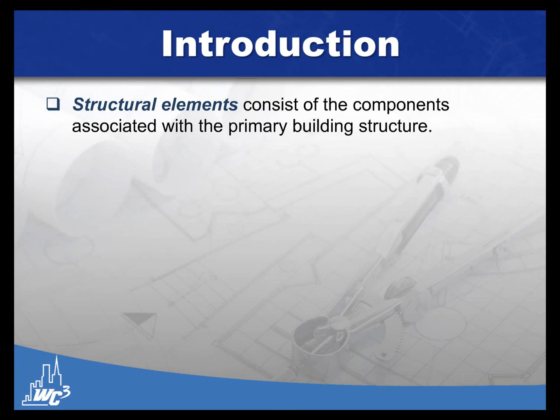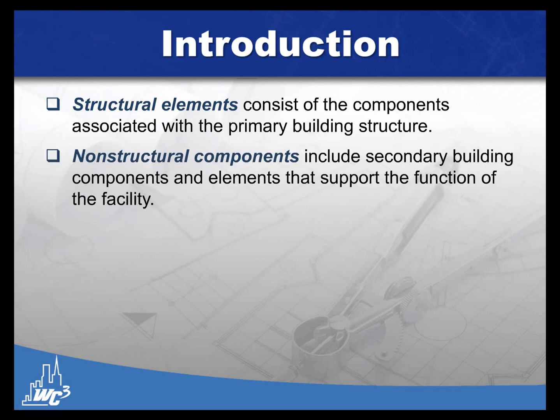All right, so structural elements. When we're talking about actual structural elements, we're talking about those components that are part of the primary building structure, right? The beams, the columns, the foundations, those sorts of things. When we're discussing non-structural components, we're talking about some secondary elements that are associated with the facility that allow it to function the way it needs to.